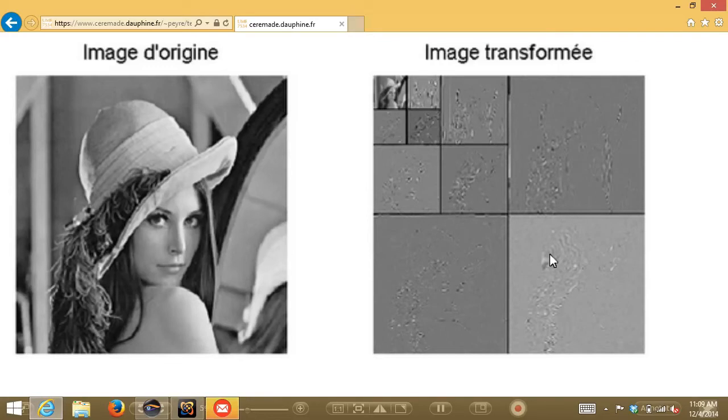And so the argument would be to compress. Maybe I might take all these edges, which are using 1/4 of the coefficients, and set them all equal to 0. If I reconstructed the image, it would look pretty much like the original one, right? And I would gain substantial compression. Or maybe instead of getting rid of them entirely, I quantize them so that instead of having 256 gray levels in the edgiest image, I only allow myself 4 levels. Then I'm saving 6 bits on 1/4 of the coefficients, and that gets me some compression gain, right? Something like that.